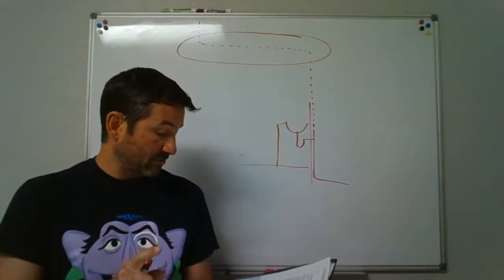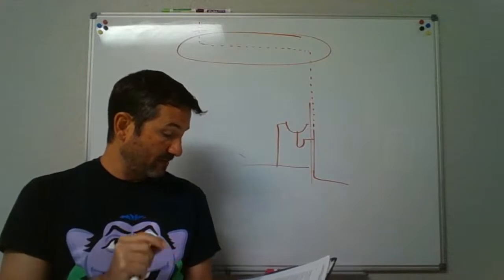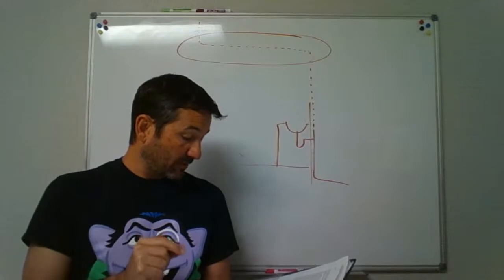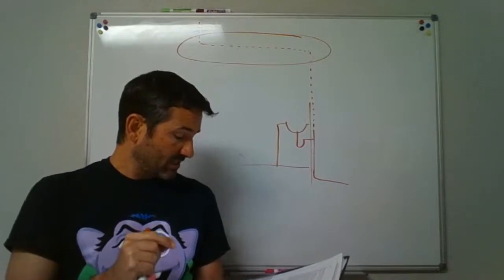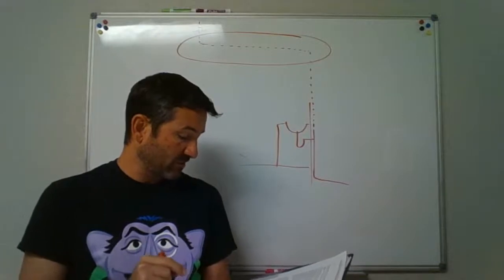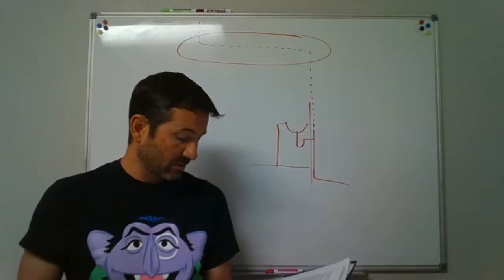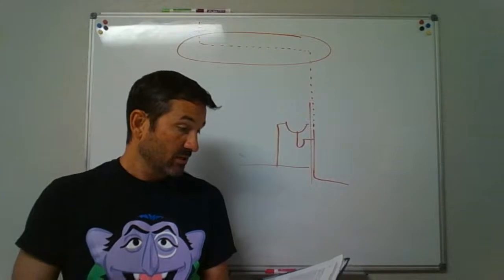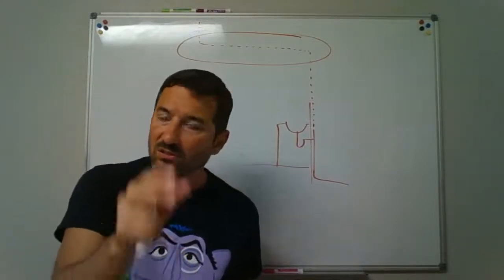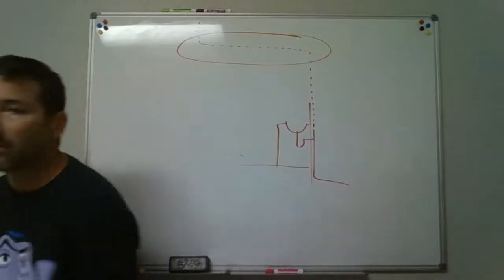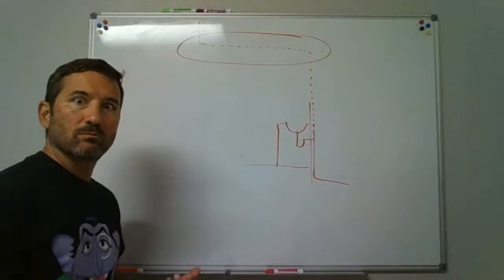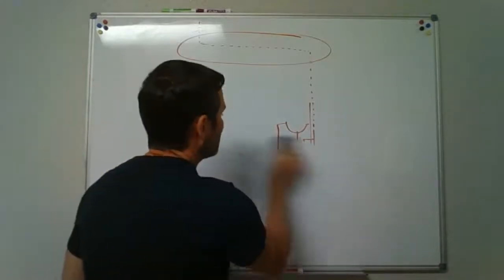Height above fixtures. A connection between a vent pipe and a vent stack or stack vent should be made at not less than 6 inches above the flood level rim of the highest fixture served by the vent. Horizontal vent pipes forming branch vents, relief vents, and loop vents should be located not less than 6 inches above the flood level rim of the highest fixture served. What you commonly hear is 6 inches, 6 inches, 6 inches. So that's what you really need to remember: 6 inches. But now you might say, where are all these 6 inches we're talking about?